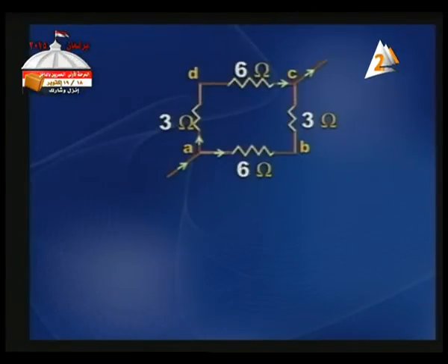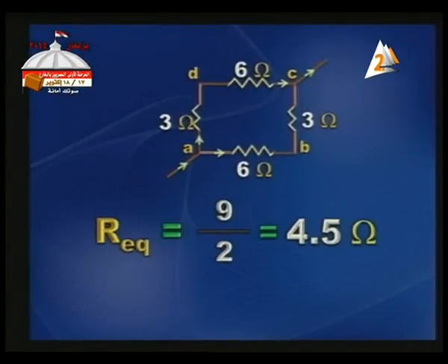And what when we connect it across AC? In this case, we've got 2 branches, one of 9 ohms, and the other branch will also have a resistance of 9 ohms, and they are connected in parallel, so it's all easy. 9 over 2, it is 4.5 ohms.